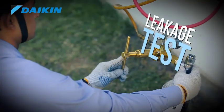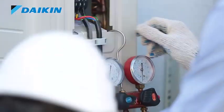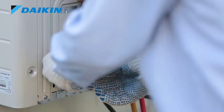Leakage test. Before commissioning the unit, leakage test needs to be performed. This is done by charging the system with dry nitrogen up to the test pressure.